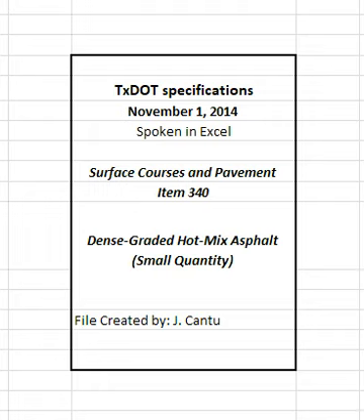4.6.3.2 Hauling equipment. Use belly dumps, live bottom, or end dump trucks to haul and transfer mixture. However, with exception of paving miscellaneous areas, end dump trucks are only allowed when used in conjunction with an MTD with remixing capability unless otherwise allowed. 4.6.3.3 Screed heaters. Turn off screed heaters, to prevent overheating of the mat, if the paver stops for more than 5 minutes. 4.7 Compaction. Compact the pavement uniformly to contain between 3.8% and 8.5% in-place air voids.